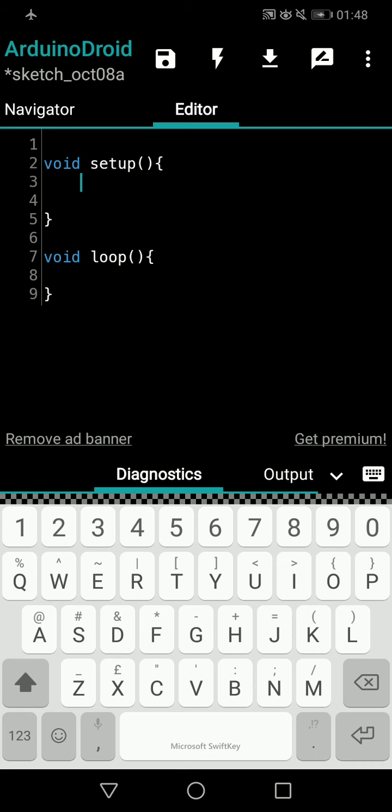So as usual, you may remember how we created digital outputs in the Blink example, and how we took analog inputs in the previous videos. Like that, to give analog output, the first thing we have to do inside void setup is mention whether the pin is an input or output. Doing it one time is enough, so we do it in void setup, because if you say once that this is an output or input, Arduino will remember it forever. You don't need to repeat it.